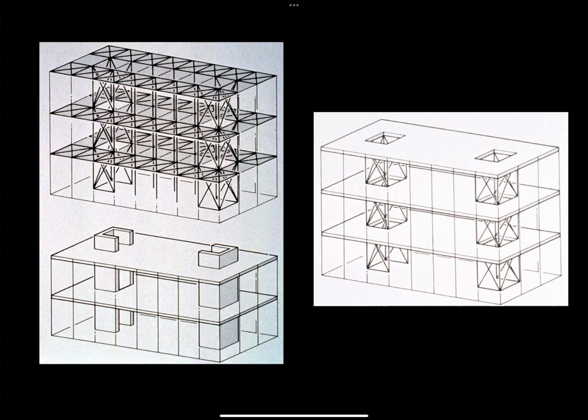So in order to make a building rigid, typically what we do is we brace the cores because we know that these go continuously from the top of the building to the ground. So they're logical places to provide lateral stability. And this strategy of bracing the cores is good for buildings up to about 60 stories. But if we want to go higher than that, we have to move the bracing out to the perimeter of the building to get a larger cross-section of rigidity.